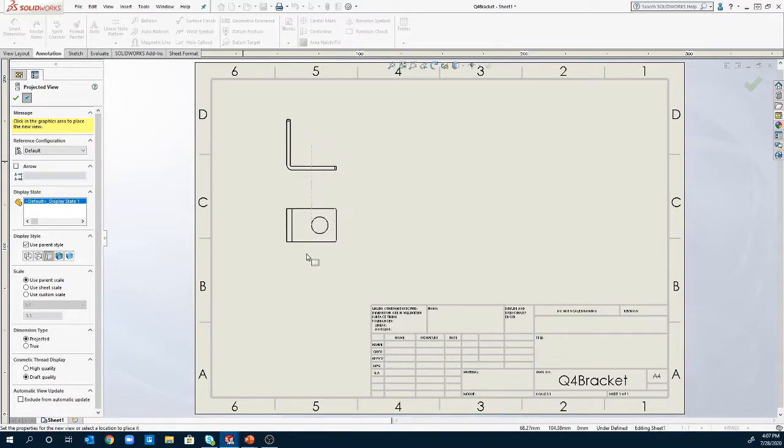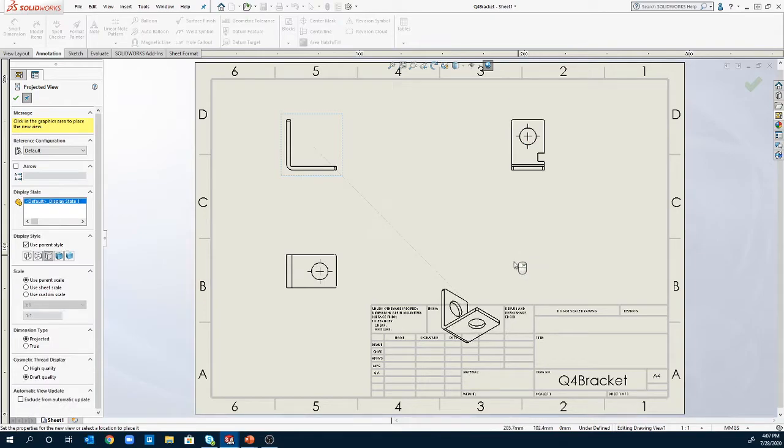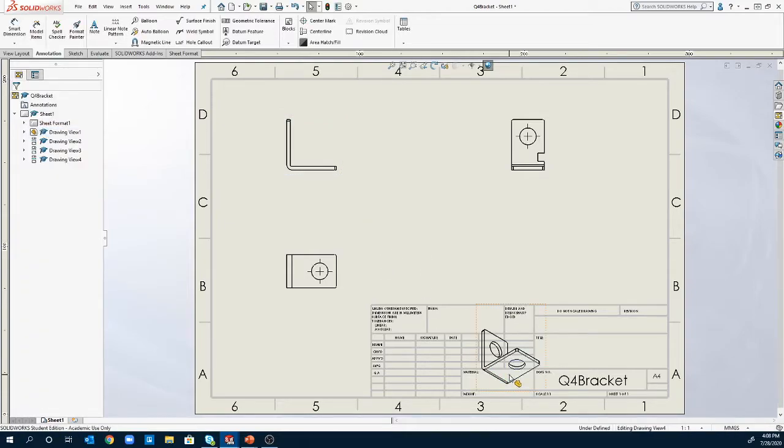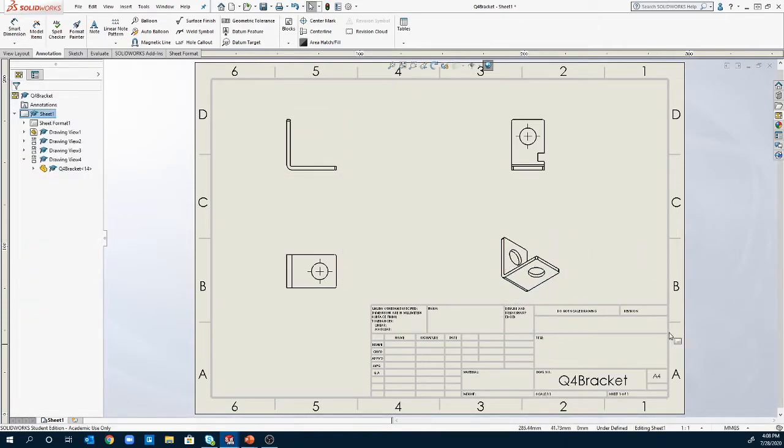If we then drag in another direction, it will automatically create an orthogonal view in that dimension. So if we do something like this, and you can put one over here, and what we'll do is place that one, and then I'm going to hit the escape key. Once we do that, we can then grab the box for this one and move it up so that it is not sitting in the middle of our block. And this is one possibility.